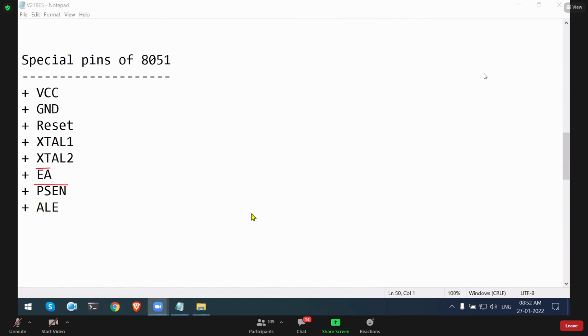Yes, you can connect a digital sensor directly to the microcontroller. The question is, can we connect a digital sensor directly to the 8051 microcontroller? The answer is yes. We can connect a digital sensor directly to any IO pin of the microcontroller. There are 32 IO pins, so use any IO pin to interface the digital sensor.